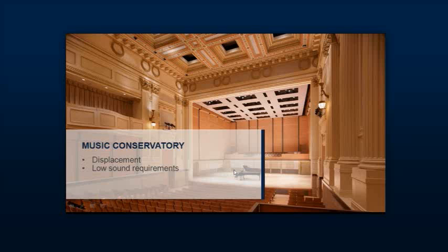All good and done. But if we were going to mechanically ventilate it, then I have to have diffusers somewhere inside the space. Now, this original mock-up request required us to put the diffusers underneath the pews of the Catholic service area. And this cathedral is actually one as well. You can see the kneelers, and you can see perhaps the diffusers directly underneath the pews. So you can imagine that if they use the kneeler, their feet are directly on top of these diffusers.